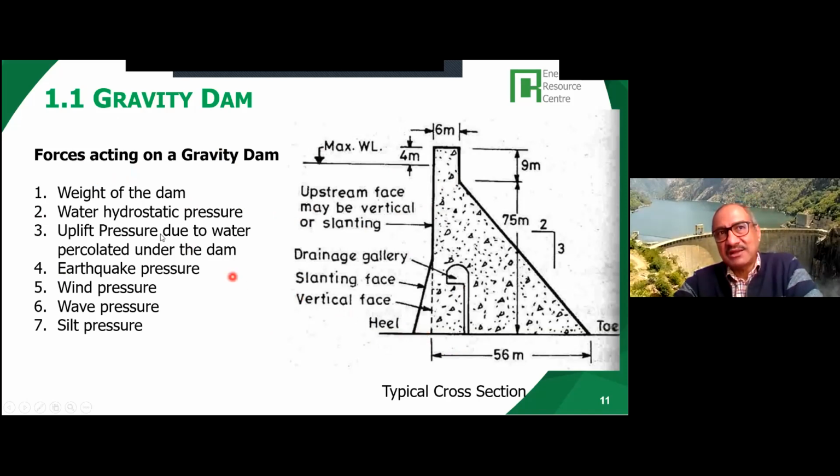Maybe I'll cover in one of the later sessions that there will be a sediment load which can fill the whole reservoir. From my experience, from the literature that I have gone through and from the information I have, there are 2 or 3 ways you can manage that. Number one is most dams have what they call a dead storage area.